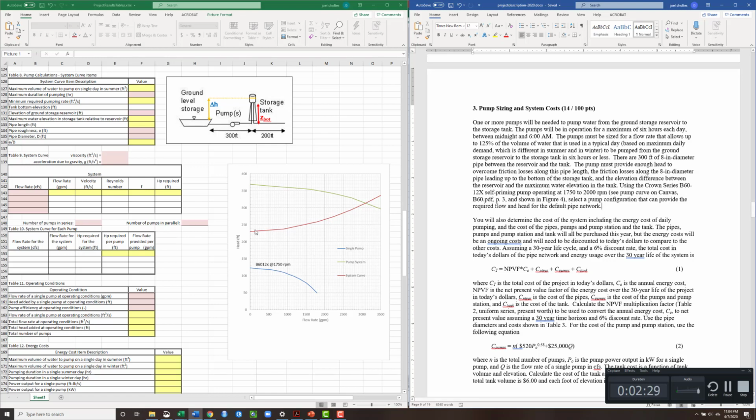And you'll use that information to develop the system curve, which I am showing here. So this red line is the system curve. And depending on the elevation of the tank, that's going to be the head the pump would have to supply at 0 feet, zero discharge. And then as discharge increases, obviously we have this kind of curved pump curve here.